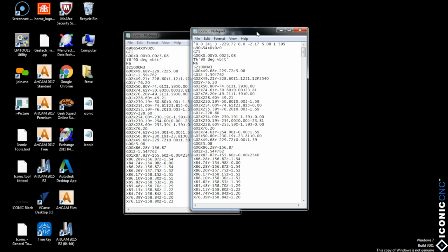So here on the left is the NC file. Here on the right is the G file. You can see that from this line to this line, they're all exactly the same all the way through the G-code. What's added here is this top line of code, and what that does is it's showing the extreme distance. So this is all in metric units, but it's showing the farthest distance on the X, the farthest distance on the Y and the farthest distance on the Z for this particular project. And the border function will actually draw a box around that XY coordinate to show you where it's about to machine. So it's kind of a handy function.